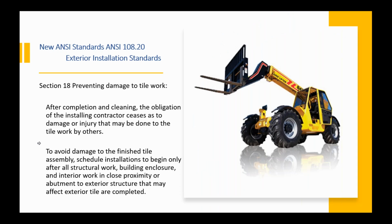After completion and cleaning, the obligation of the installing contractor ceases as to damage or injury that may be done to the tile work by others. So once you're done and off the job, it really shouldn't be your responsibility to protect that. Avoid damage to the finished tile assembly. Schedule installations to begin only after structural work, building enclosure, and interior work in close proximity or abutment to the exterior structure that may affect the exterior tile are completed.